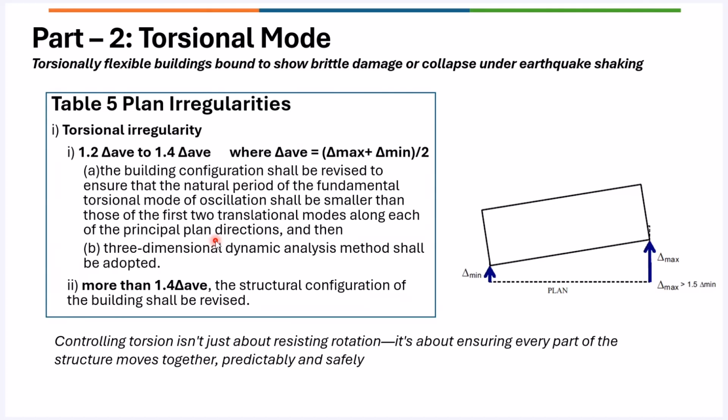So we need to do advanced analysis like time history analysis, and we'll be using tuned mass dampers to control the torsional excitation or the response of the structure.